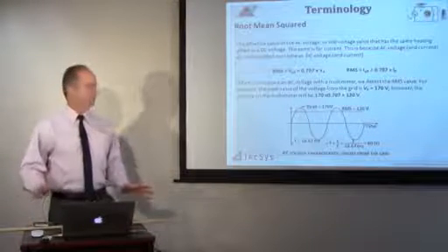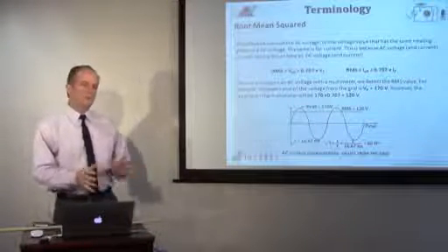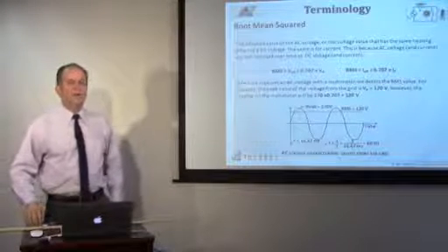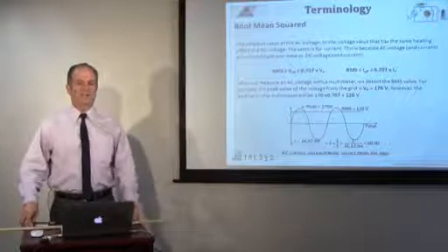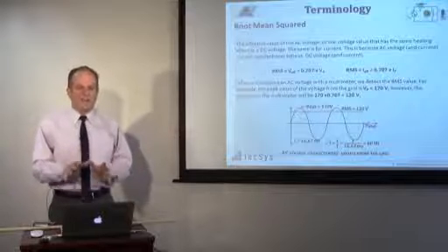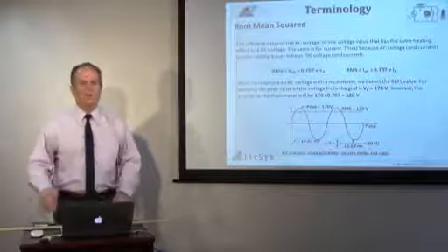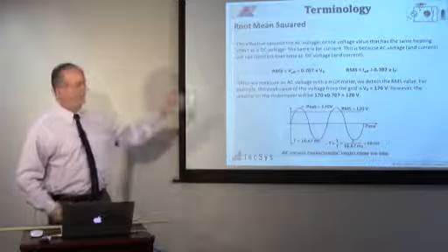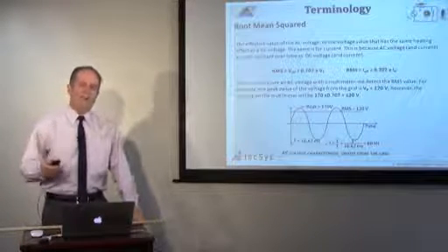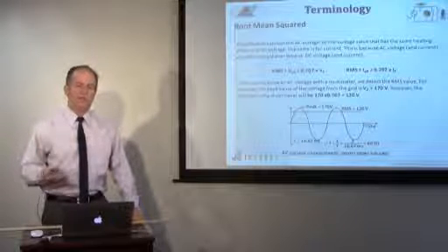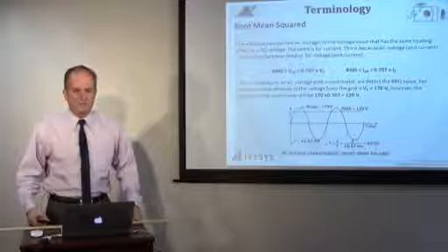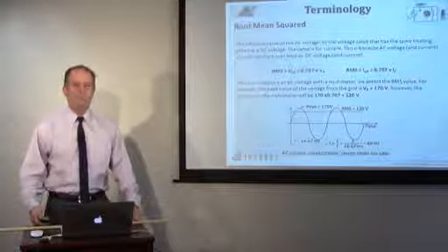The equipment is that fast. It's protective relaying and everything associated with it. So timing is important, because when there's a problem out on a system, we want to be able to open up that problem and disconnect that problem right away. So when we talk about frequency and timing and RMS, we're getting the foundations for talking about the big bulk power system later. Okay, so that's what we have to deal with on AC, RMS, and that's what all of our power lines are based on, whether it's 12 kV distribution, 345 kV transmission, or even 765 kV transmission. That's all RMS. Okay?